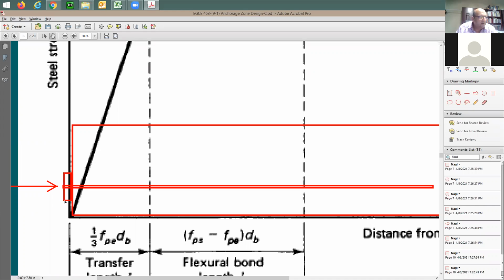So in pre-tension, you're going to have direct connection between the cable and the concrete itself. So I can remove this because it's not really needed in pre-tension. And I can make this short because they're going to trim the cable, cutting it to be exactly this length.